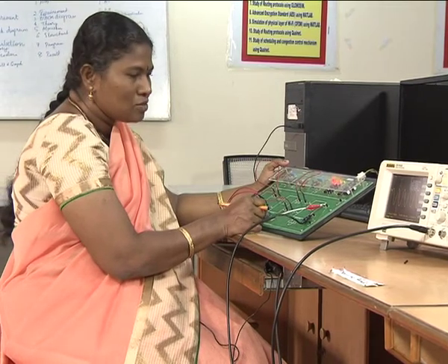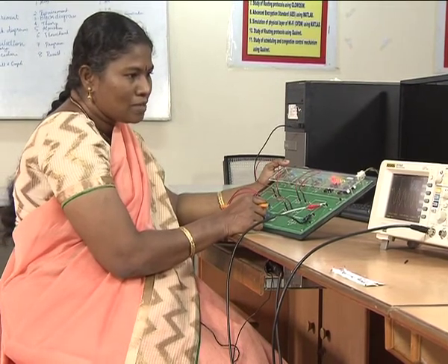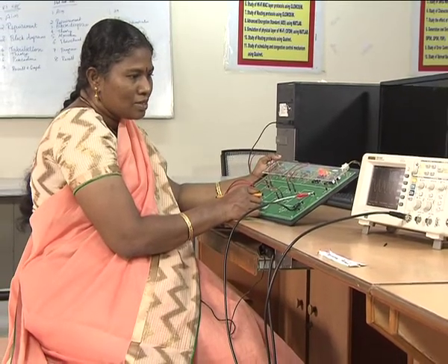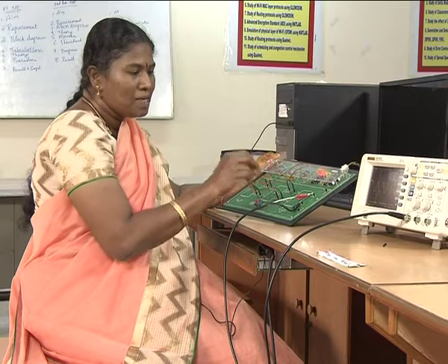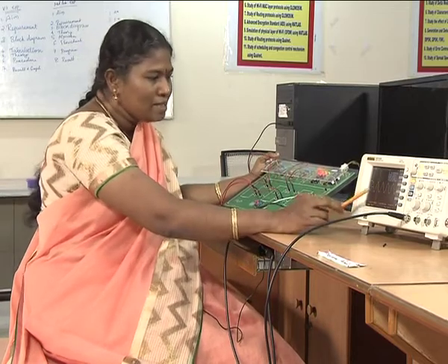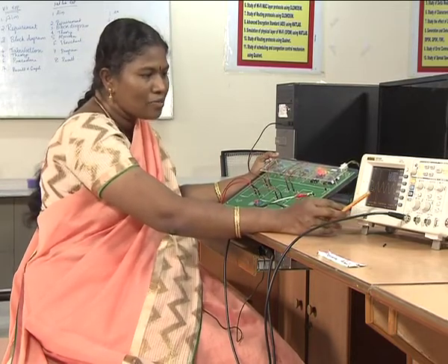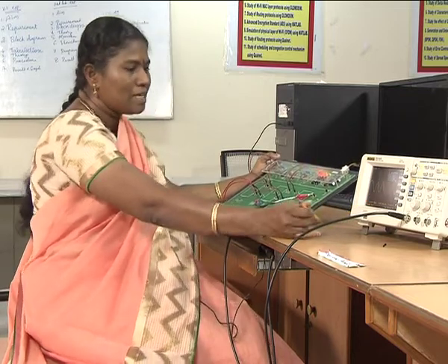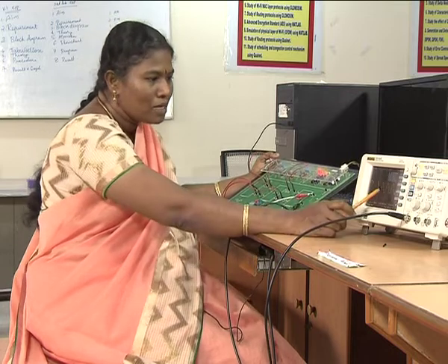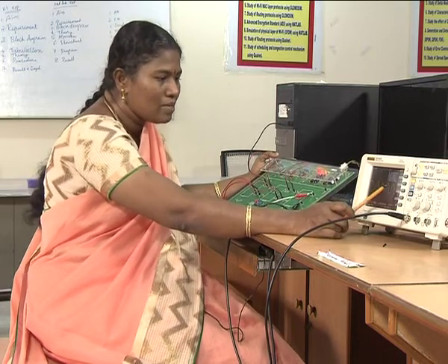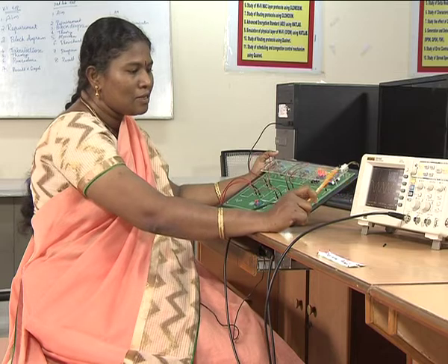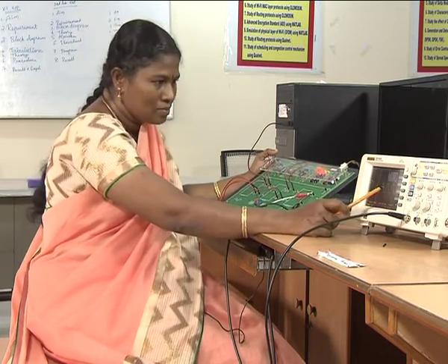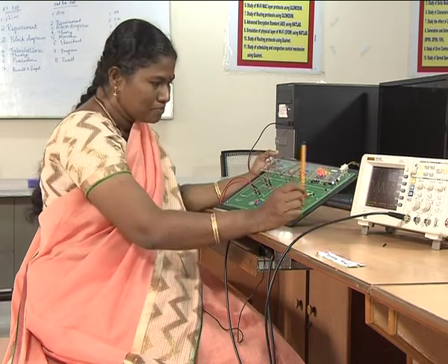You can see that as you adjust the knobs, the amplitude of the output signal changes. This is the demodulated output at the output of the PLL. Now, you measure the peak of the sine wave and draw the demodulated output signal. You can draw one FM modulated signal as the input to the demodulator, and the output obtained here is a sine wave proportional to the message signal that you provided to the FM modulator. You can draw this waveform as the FM demodulated output.